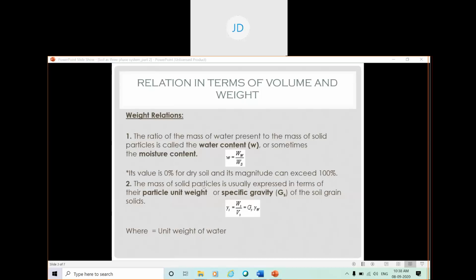Yeah, where am I? So I think you have got these things right. Unit weight of solid. Unit weight of solid. Fine. Now I'll come to this. You don't worry about this term, that is Gs and gamma w. What is this? I'll tell you now. So I think till now you have understood this. That is, unit weight of solid is represented by dividing weight of solid by volume of solid.